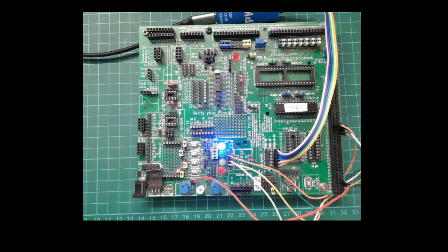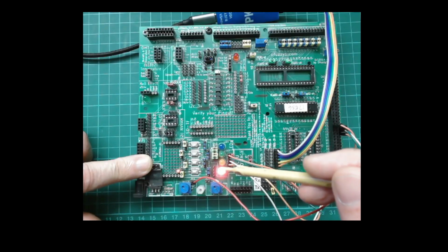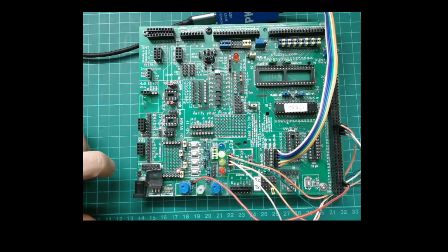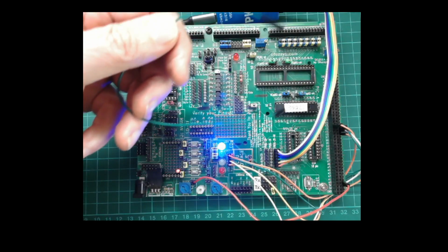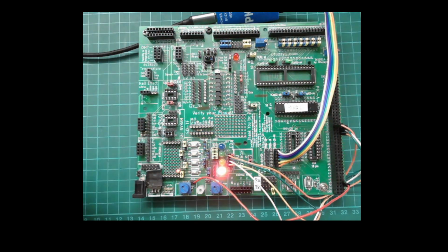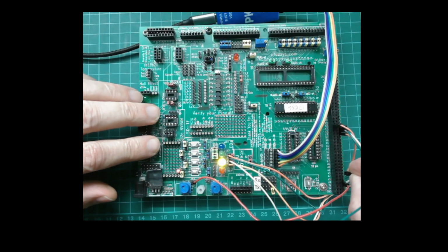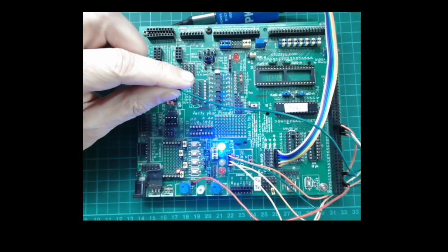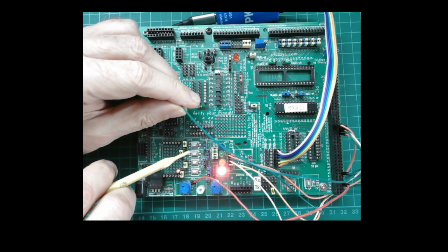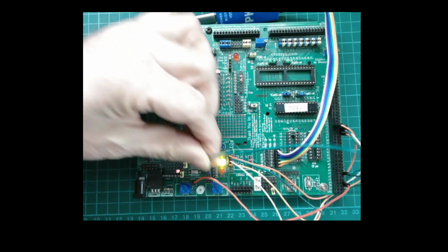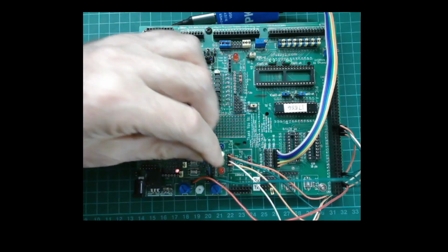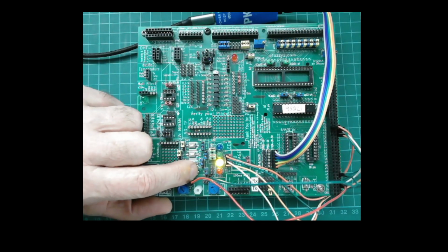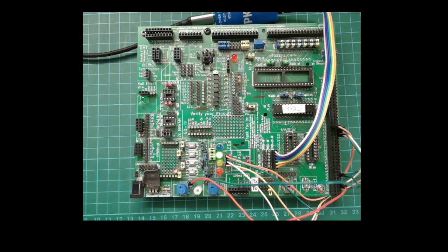My pointer's here. So I have 4 LEDs here. What we're interested in today, we're going to toggle those on and off. And I'm going to connect, let me just grab a cable, I'm going to create a flying lead like this to port A3, which is over here on the right hand side. Hopefully you can see me connecting that. And I've got a set of switches here. Some of these are pulled high, some are pulled low, but I know that my lower switch is pulled high. So I could push that at any time, and I'm actually toggling port A3. Now, this is the old tutorial, so obviously nothing happens. And we'll have a look at that change.